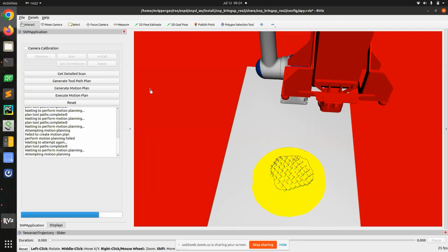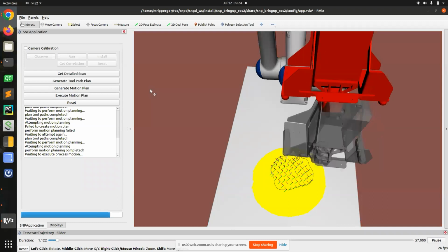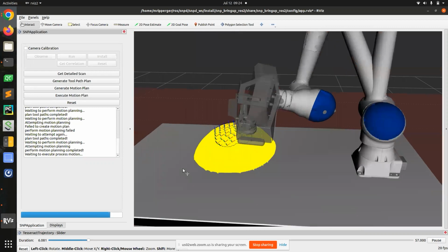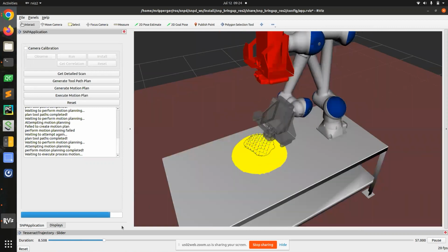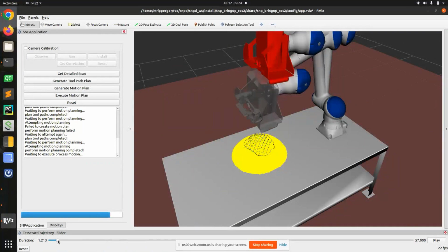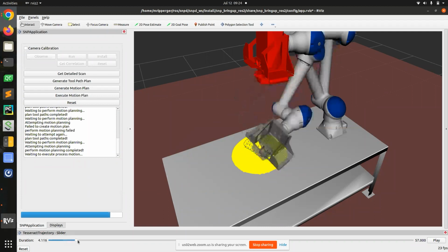Yeah, so it's sort of a cool aspect of the motion planning capabilities of Tesseract that it lets us try lots of different things and optimize our planning efforts, right? If we can do things joint interpolated and they're collision free, then maybe it doesn't actually make sense to push those through other planners. Or maybe we do run it through Descartes and then try to smooth it with TrajOpt. And so there's a lot of cool options that we have, and maybe we should make that its own discussion at some point. Yeah. Because there's a lot of content there that people might be interested in.